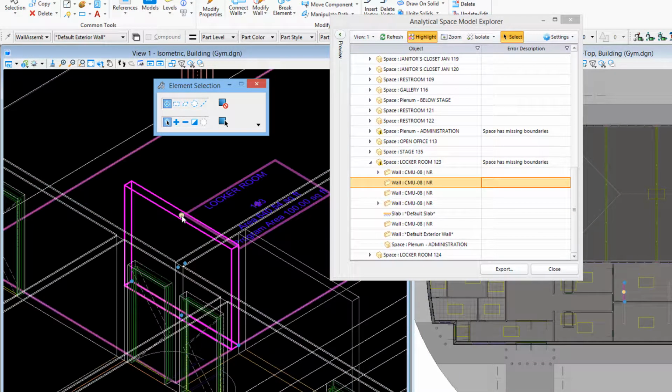If I just hover over that top handle, this is a linear form, this wall. And so the top of it, it considers that to be the roof of the form. Don't get confused that this is the roof of the building. This is just the top or roof of the wall. And I can simply left click as I hover over that handle.